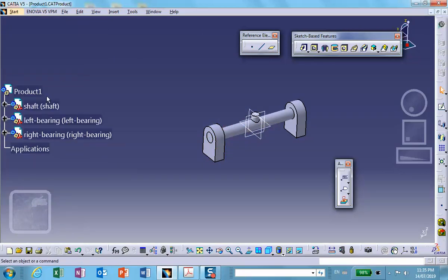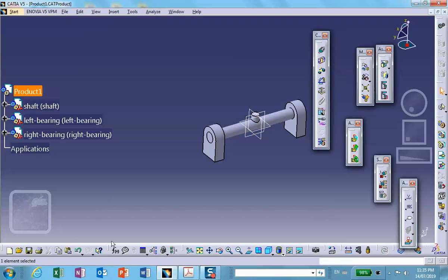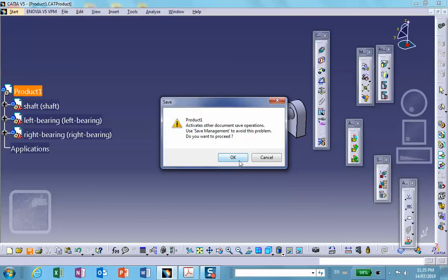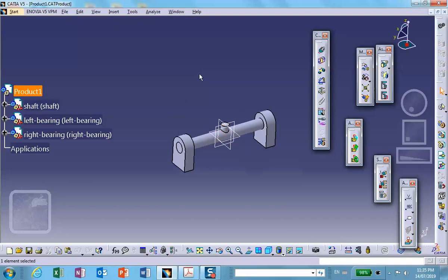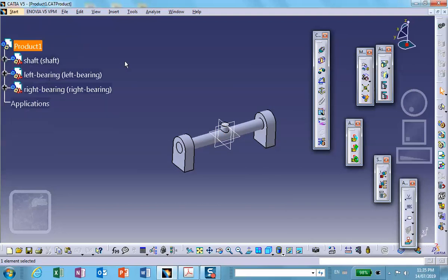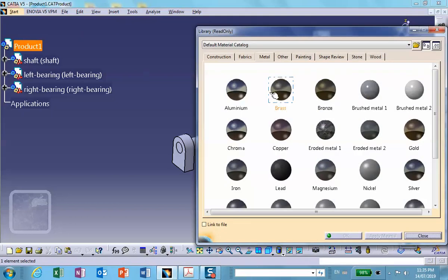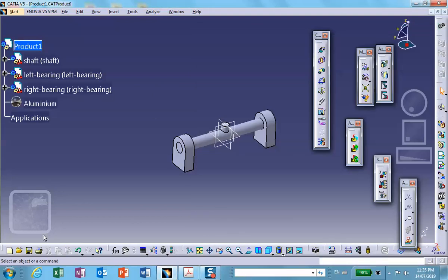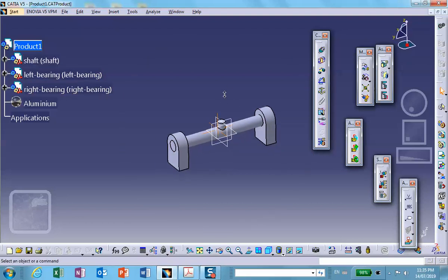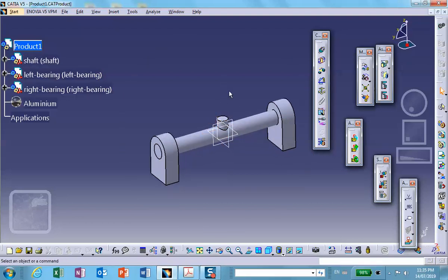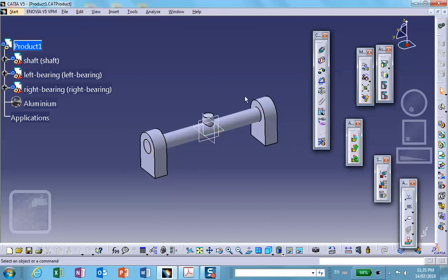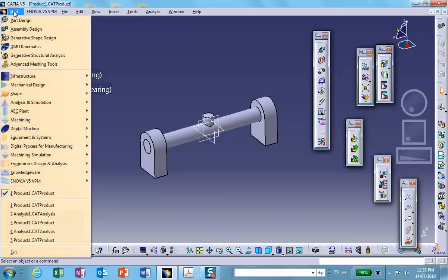Go to the assembly level and save everything. Let's make the entire assembly made out of aluminum, with default material properties. So apply material, metal, aluminum on that assembly, and then close it. Okay. So everything is made. The only difference between what I have here and what's in the book is that the length of this shaft is larger, and also there is no stand in the book, so the load is applied on the entire shaft, which is not realistic.